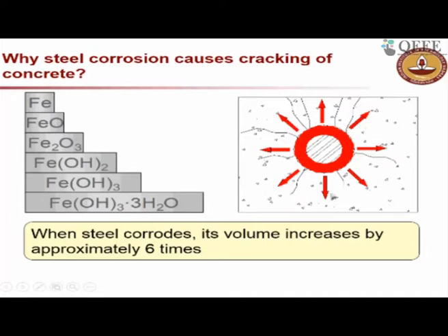Now, is it good? In one way it is good that it leads to some cracks, so that we can actually see that something is wrong. But on the other hand, we can also think that if this crack is not there, then it will take longer for that steel to corrode. So you have to judge on that.